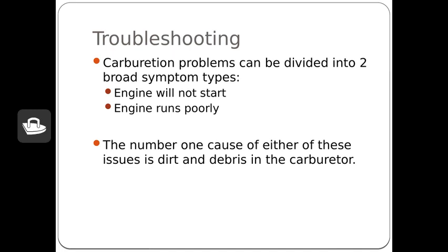And sometimes it might be a time to either take it to a technician to see if they can get whatever is in your jets out, or sometimes the technicians will even tell you, yeah, I can fix this, but it's going to be cheaper for you to just simply replace your carburetor. A pretty standard Briggs carburetor is going to run somewhere between $30 and $50. The time it would take a technician to disassemble and clean the jets, at an hourly rate, would probably run more than that.